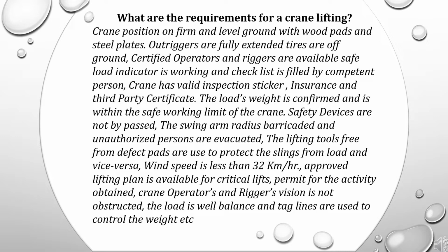Safety devices are not bypassed, the swing arm radius is barricaded and unauthorized persons are evacuated, the lifting tools are free from defects, pads are used to protect the slings from load and vice versa, wind speed is less than 32 km per hour, approved lifting plan is available for critical lifts. Permit for the activity obtained, crane operators' and riggers' vision is not obstructed, the load is well balanced and taglines are used to control the weight, etc.